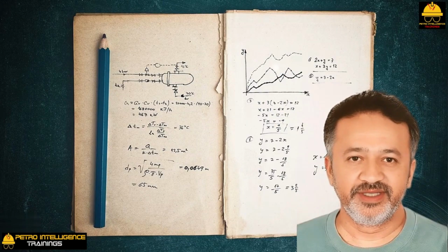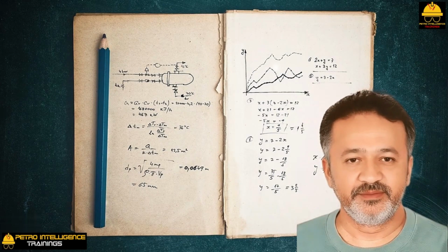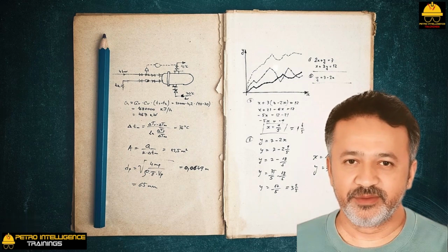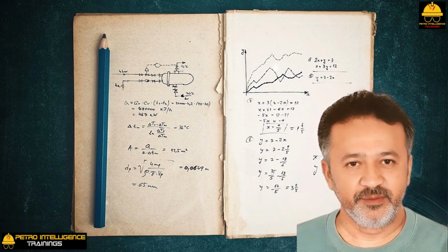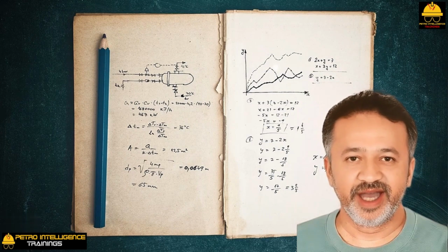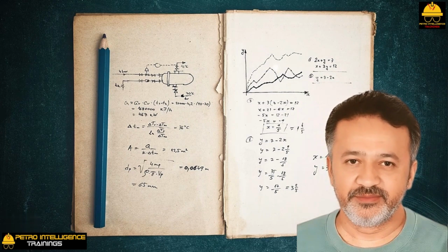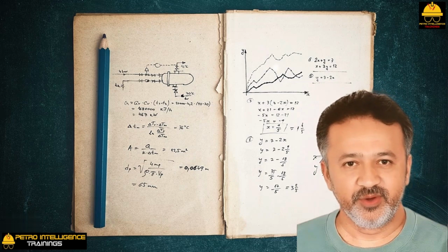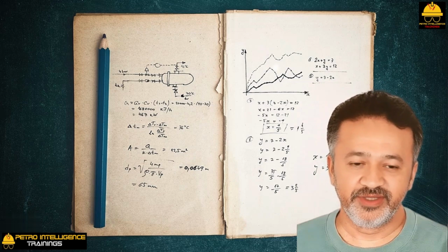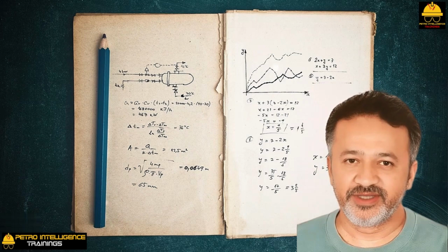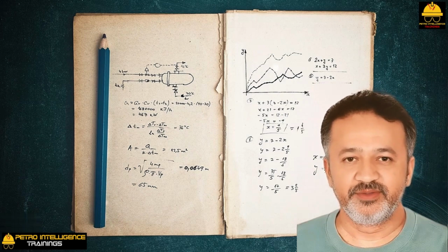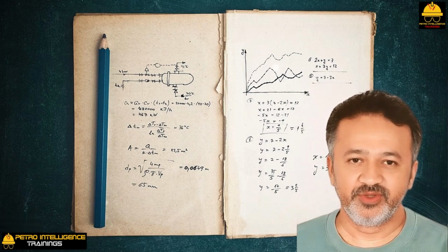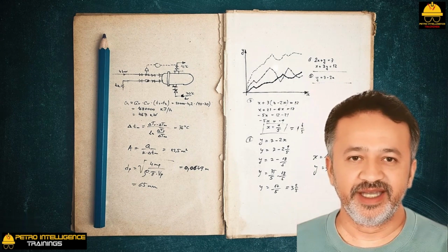Why is thermodynamics important to the plant operator? Machines are not driven by the heat of steam, but by the velocity of steam. Mainly, I am referring to steam turbines used to drive pumps, compressors, air blowers, and electrical generators. It's the velocity of the steam striking the turbine blades that causes the turbine to spin. The greater the velocity of the steam striking the turbine blades, the more work can be extracted from each pound of steam. The application of thermodynamics in the process plant is intended to maximize the velocity of steam.